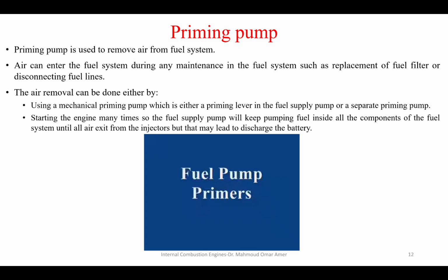The pump will try to increase the pressure, but when it compresses, the fuel or the liquid will just compress the air bubbles inside the line, and the air bubbles volume will decrease, thus giving more volume for the liquid. So when the liquid's pressure should increase, it will not increase. So the system won't operate efficiently.